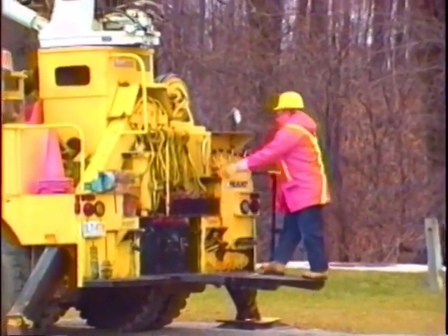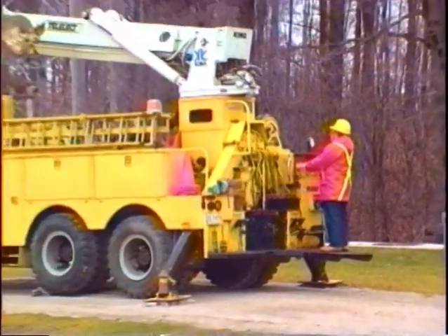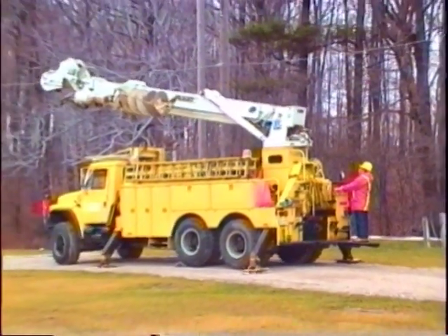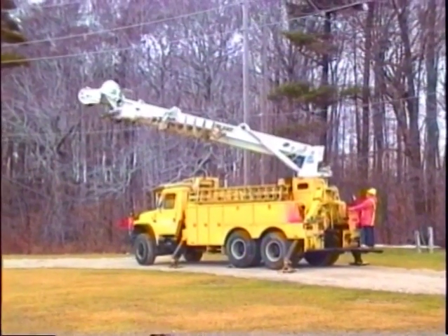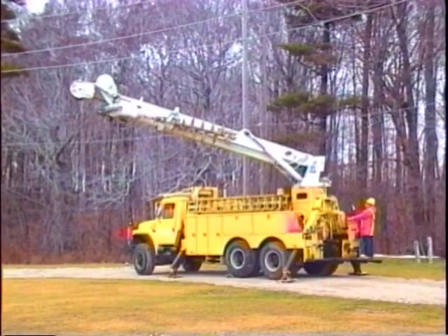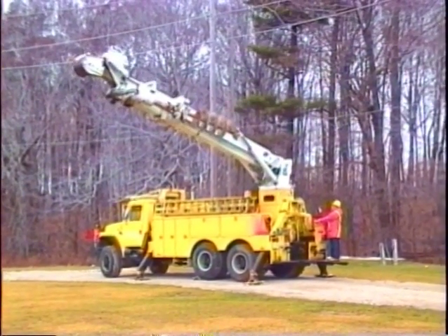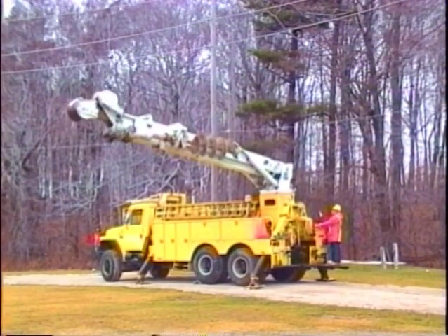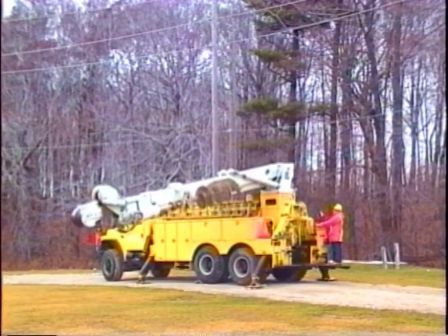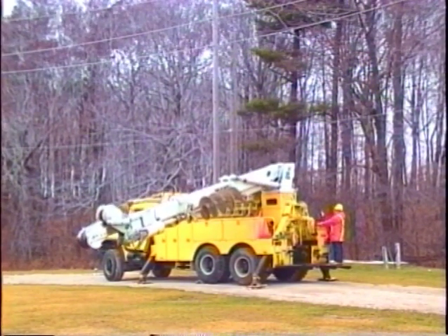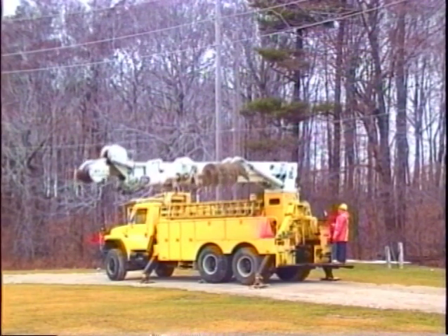In this final section of the program, we will touch on some of the ins and outs of hydraulic equipment operation, starting with vehicle warm-up. The rule about warming up your hydraulic system is simple. Do it. Run the system through its paces before starting work. Give the hydraulic fluid a chance to circulate. If you are working in cold weather and have to shut the system down for more than an hour, go through the warm-up procedures again before starting work.